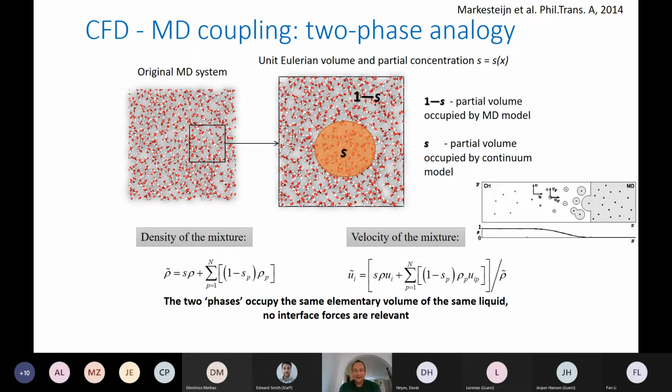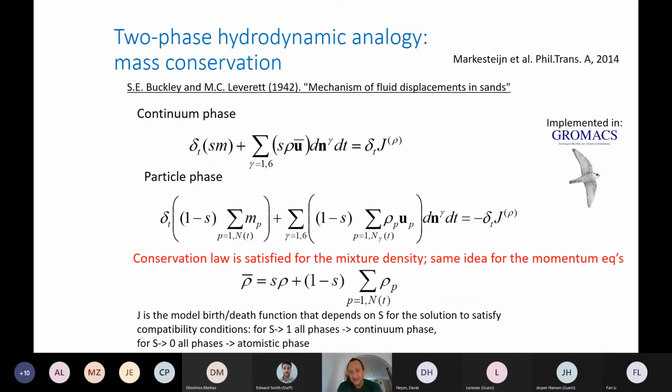1. So then you can formulate the equation for the conservation of mass or concentration and conservation of momentum using the classical two-phase flow liquids. And you would have something like is written here. So the change of mass plus the divergence of all the fluxes, mass fluxes in this case, is equal to some sources which appear because you can allow the second phase to transfer to the first phase. So that's sources which you can have in miscible phases.